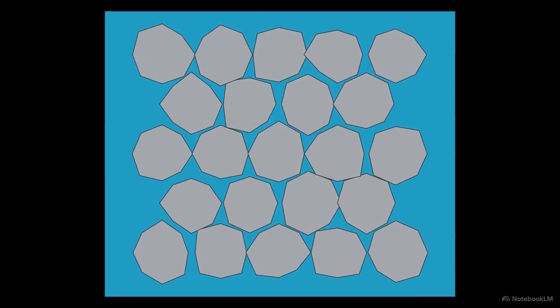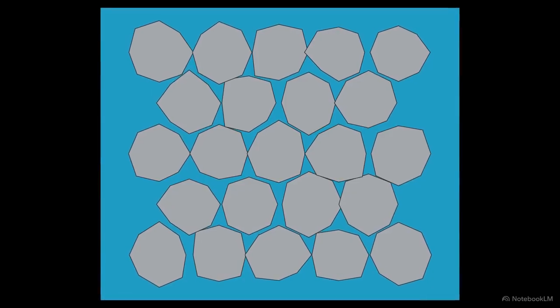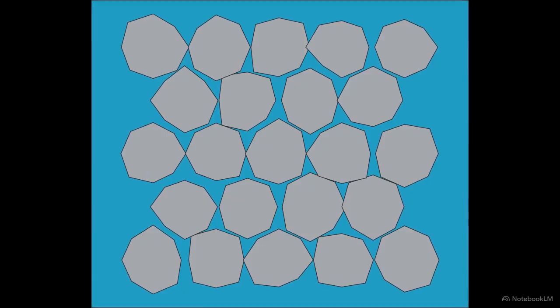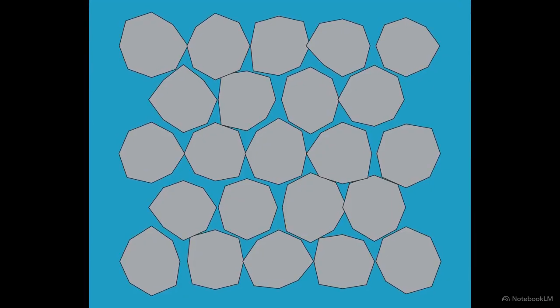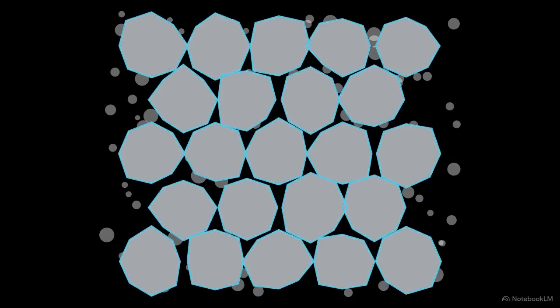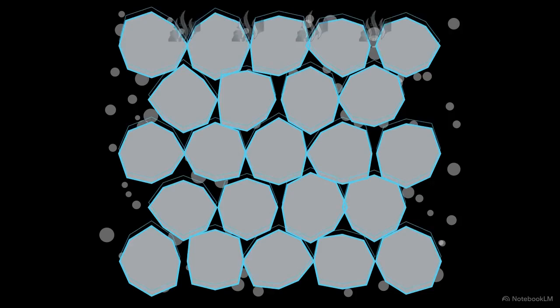Drying is no longer limited by how much vapor the air can absorb, but by the physical transport of liquid from the core of the material to its surface. The bed has entered the funicular state. Air now occupies the internal pores of the bed, and the remaining moisture exists as thin, continuous films clinging to